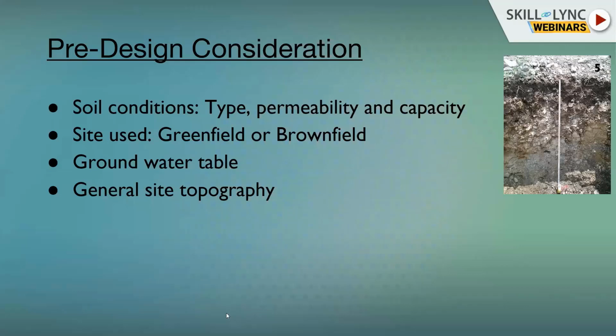So we know that if the soil type is clay, the infiltration is very less. So we cannot do anything about it. We cannot infiltrate any water. So we have to think of a different component of SuDS, which does not concentrate more on infiltration, but on some other technique. So for soil conditions, we'll see the type, the permeability rate, and the bearing capacity, of course, because we'll put some structure, so we should be knowing how much load the soil can take.